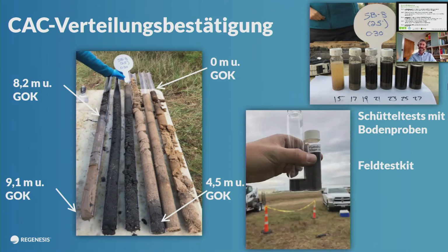And there's a field test kit as well where you're looking at the groundwater, and you can test this by the monitoring wells or go in and test using direct push. And you look at the color of the water, compare it to a standard concentration of plume stop that we have, and you can then see what level of plume stop you've got in the ground, so you can see that you've got the interlocking radius of influence that you need.